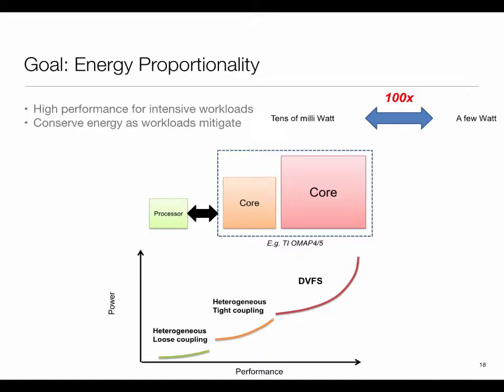While in theory the instruction set is the same as the big guys, and you can take code and run it in both directions, these are so resource starved, with kilobytes of memory and those kinds of things, that you really have no hope of them running under the same operating system management. You cannot offer the same software environment, and so these need to be more loosely coupled. There are plenty of examples of these. They usually get used for the more specialized parts of the system, or perhaps this is the only thing which may be active when you are in a really deep sleep mode.